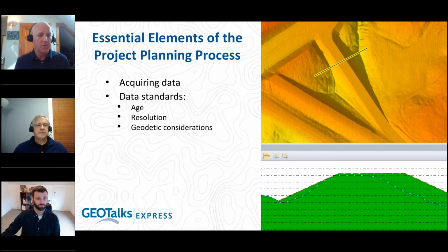Scott, this brings in your sphere of expertise where we talk about geodetic considerations. I want to have you maybe expand a little bit on this idea of addressing where the data actually resides. Is it in the right location, I guess, is the question. Sure. All of the data that we've got, some raster data, vector data, we want to make sure that all of these are in commensurate horizontal and vertical coordinate systems, which means that we need some metadata from the existing data that we have, and hopefully it's accurate, hopefully it exists, whether that be in file headers, well-known text, PRJs, or other metadata.